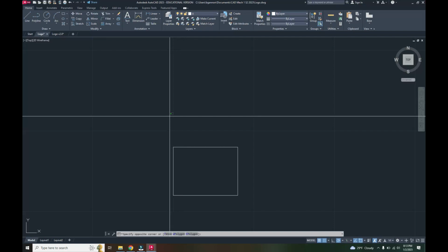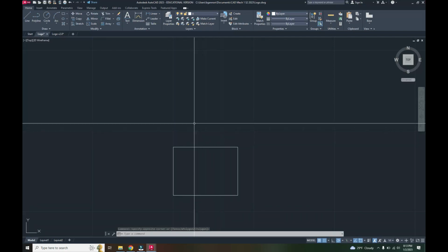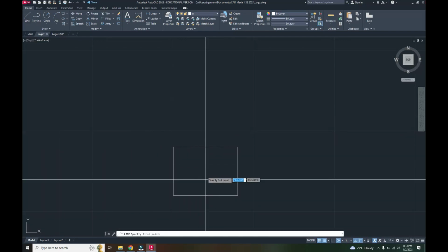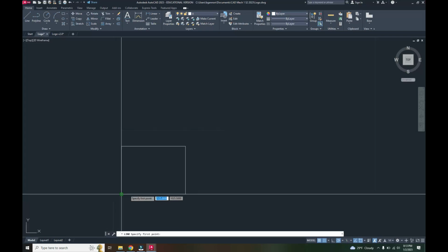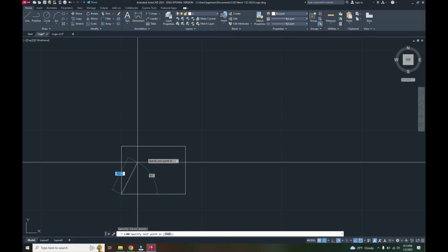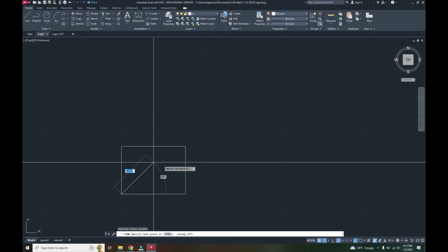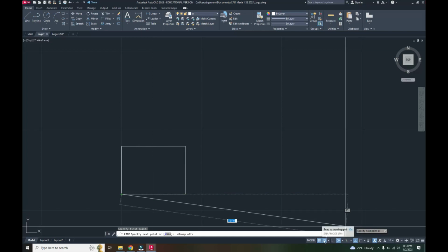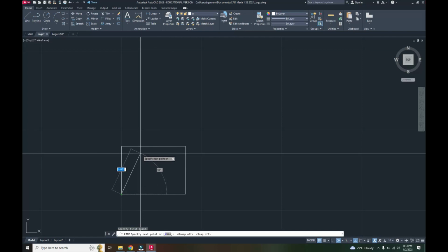You can use circles, lines, text, or a hatch fill if you want to. But simply I can start with the line tool here, and let's say I want to create some mountains. I'm going to start down here in the lower left, and you can see it clicks on there. I'm going to turn off my snaps down here. Object snap, I can turn that off, and you can see what this does a little bit. I think it's snapping to my grid. Okay, let's turn off that snap to the grid.